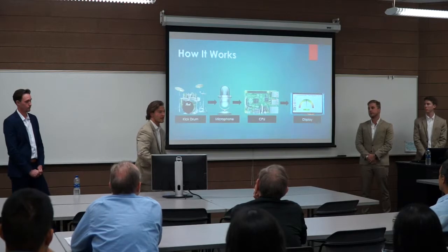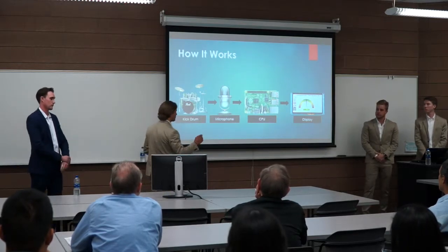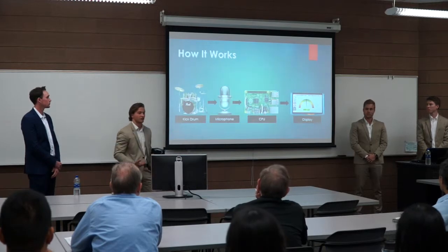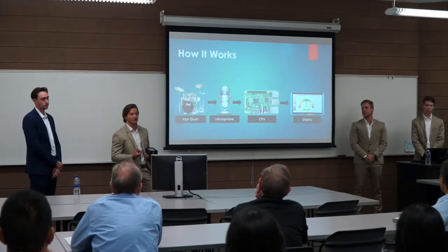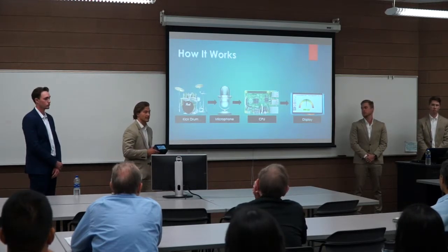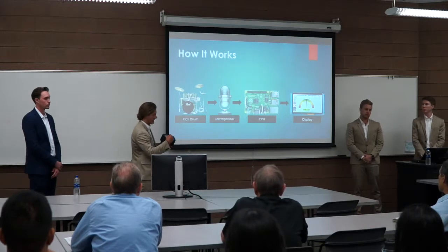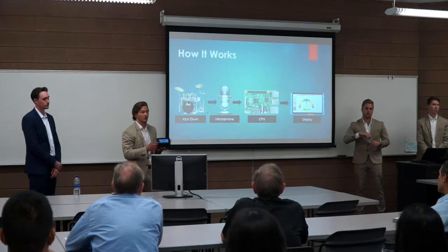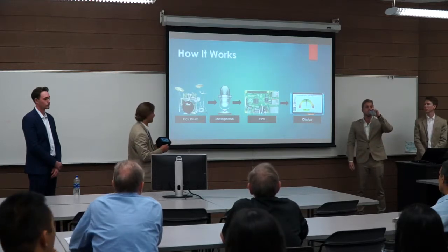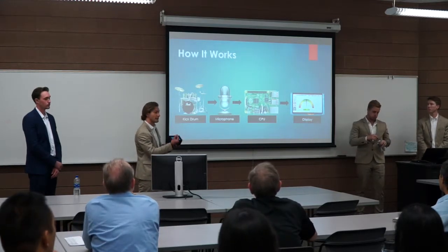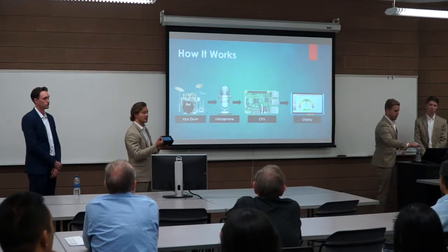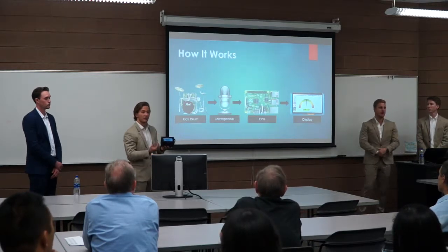So how it works, as you can see from the video, initially the drummer puts in the user input and starts playing on the drums. And like Andrew described, it is the kick drum that we're focusing on. In our device, and we can get into it later, we have an Adafruit I2S breakout board that is a microphone for sampling the actual user audio while he's playing. And then this takes the audio and puts it into a .wav file.